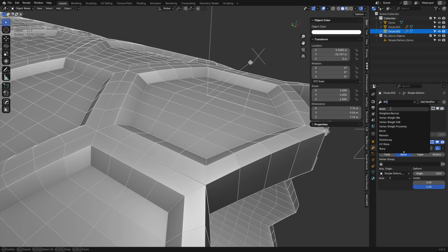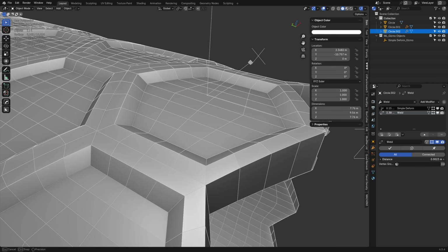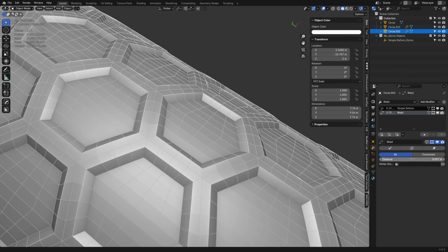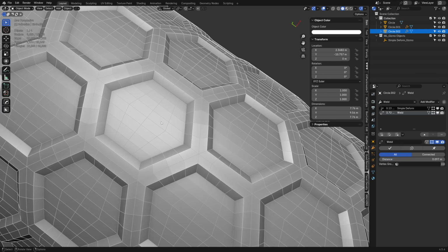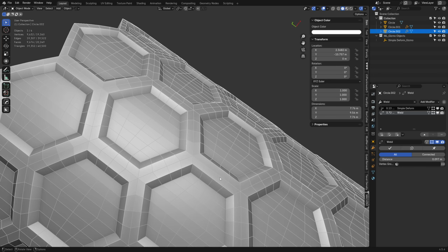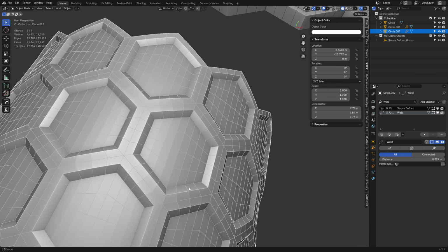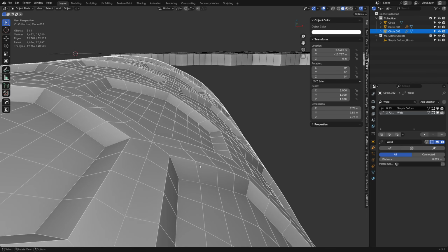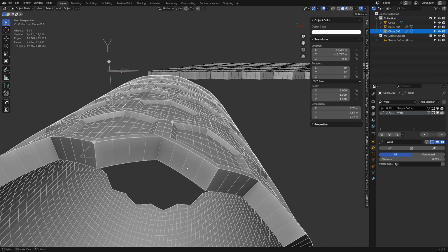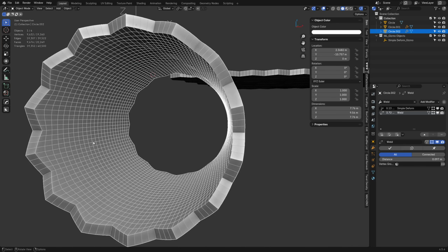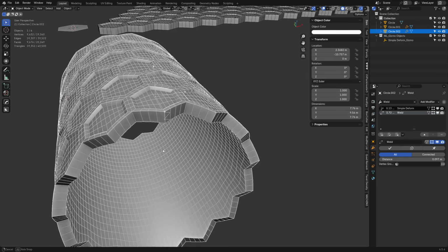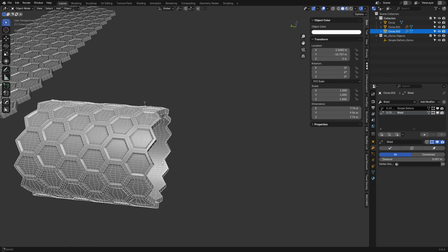We add a weld. You want to crank up that value a little bit until those all weld together. Okay. You can see the little edges. They should pop together. In our case, they might be slightly off from our weld previously, or like that spacing we had with that array would probably do that. So you want to get them very close together anyways. There'll be a slight discrepancy, that's all I'm saying. And you can see why having that more appropriate spacing would also work very well. Right? But it's welded together now, which is good.